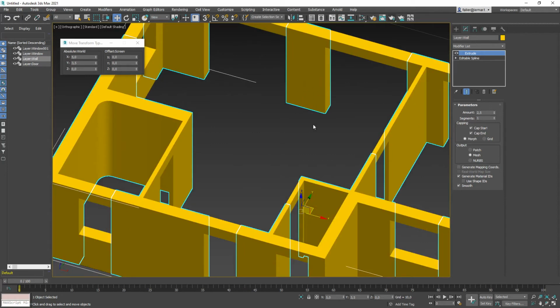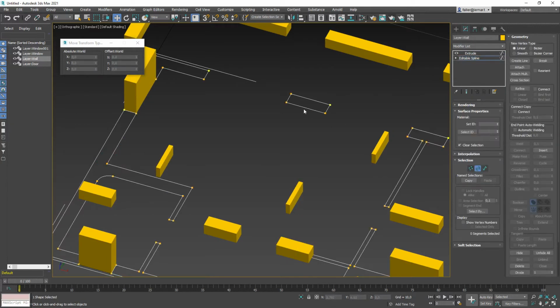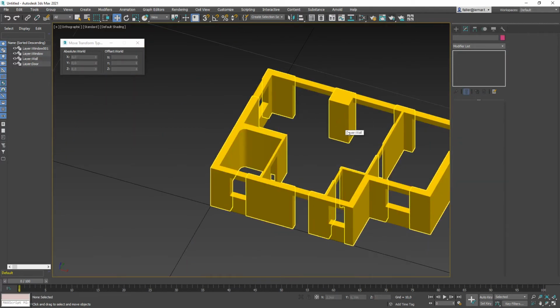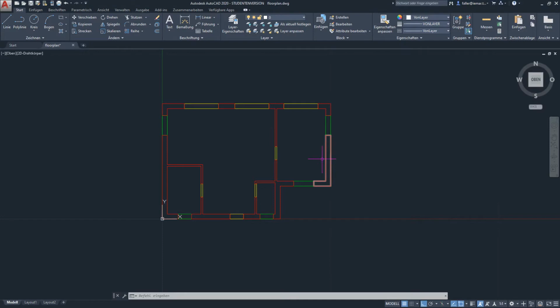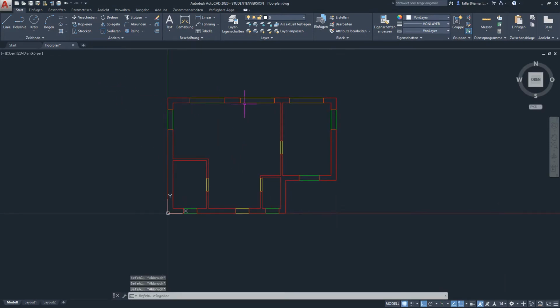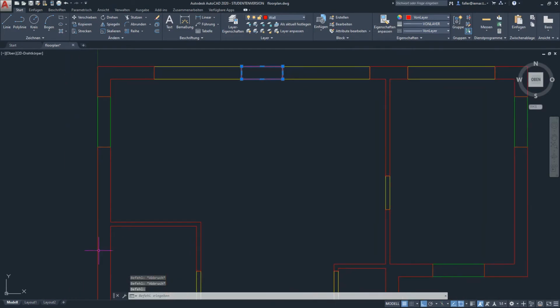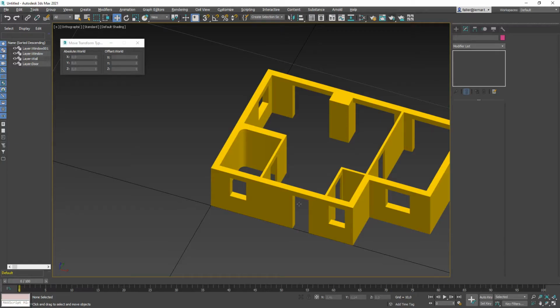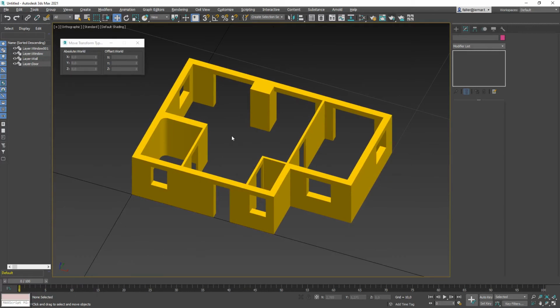Or let's say I need a thicker wall here at this piece. Select, go back to spline, select this wall, make it thicker, and here we are with the larger column there. Okay, so you can perfectly edit it and so on. But of course, I could anytime go back into my CAD file and do the same thing here. So, edit this or add a fillet there and so on. Much better. You can work to scale, and the CAD program, of course, cannot substitute what we did here in Max. Good. So editing is always possible when it is already extruded.